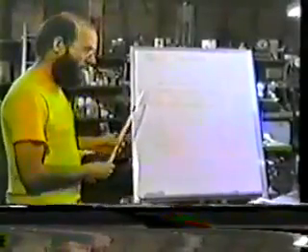So we'll review our test setup here. What we have, we've taken our element that we've shown and compiled these in series to produce on the workbench effectively 31 miles of transverse electromagnetic transmission line. This might be the power line between the substation and load, or it might be a telephone line connecting two towns together. We have our audio oscillator. We have a stereo power amplifier hooked up for mono, and that is our generator, and we've left the end of the line open circuited, so we're dealing with a quarter wavelength similar as before.